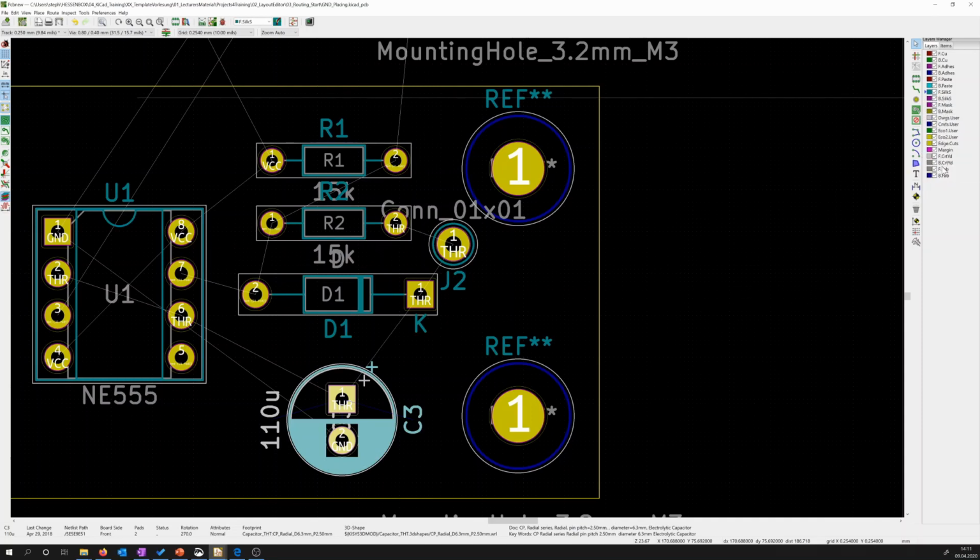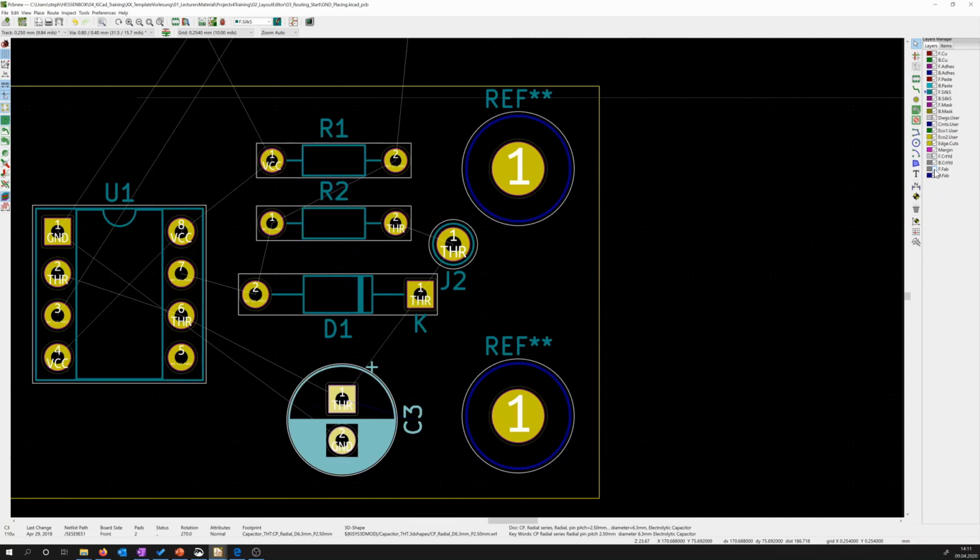Something only interesting for the fabrication and the assembling is the gray portion. So about this writing we can just deselect it, and we don't have to care about it anymore, since we don't see this later on the printed circuit board. It's only for fabrication. Since we are not going to fabrication externally, we can neglect this layer.